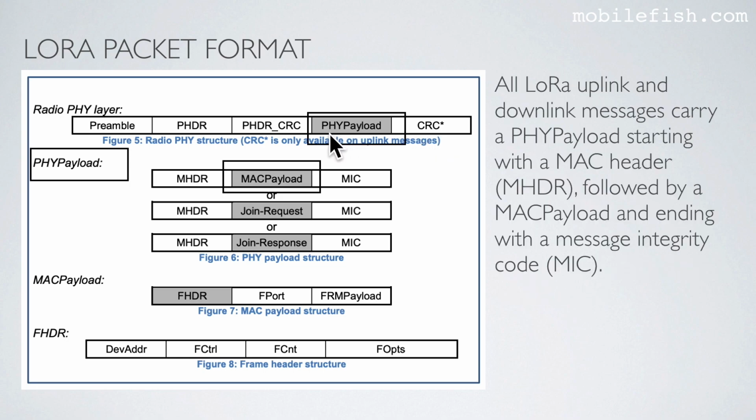Let's zoom into PHYPayload. PHYPayload is this PHYPayload, and this is PHYPayload. All LoRa uplink and downlink messages carry a PHYPayload, starting with a MAC header, followed by a MAC payload, and ending with a message integrity code.